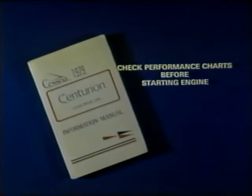It should be noted that it is possible to damage the engine if the manifold pressure is too high for a given RPM setting. Always refer to the aircraft's engine performance charts and operator's manual before operating the engine.